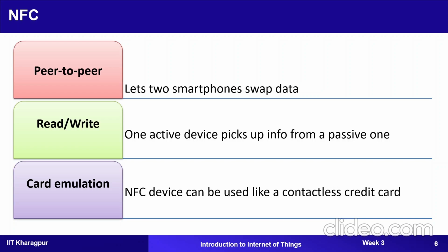So yeah, we have discussed four different modes of Bluetooth in which your Bluetooth devices work. Now after that we will discuss the various layers in the Bluetooth protocol. The first layer is your baseband. Baseband is the physical layer of Bluetooth, which is used to manage all the physical channels and links.